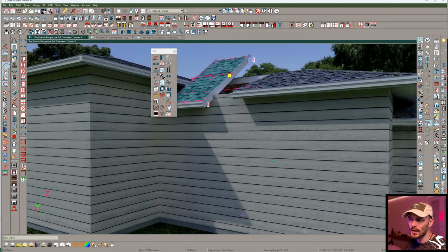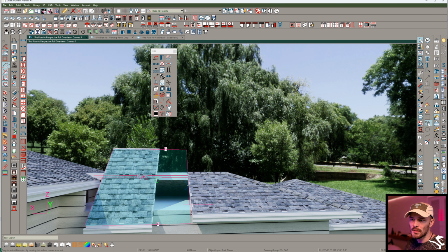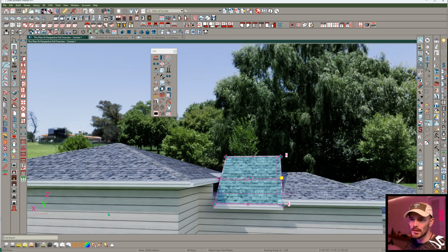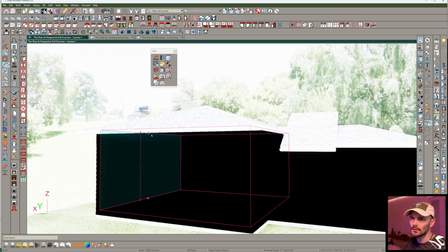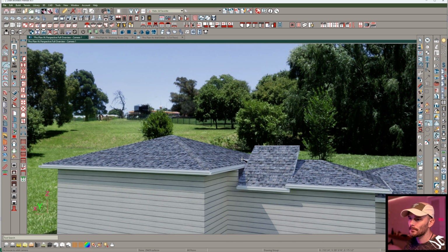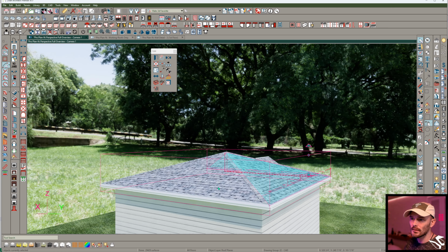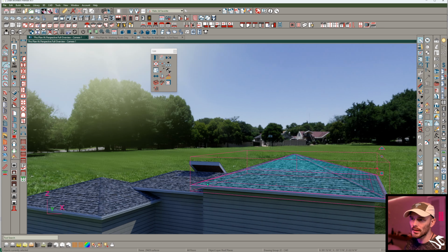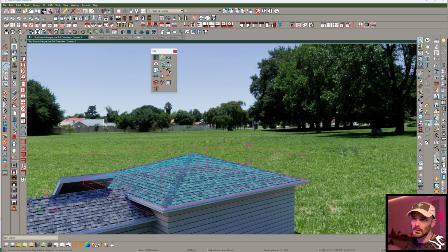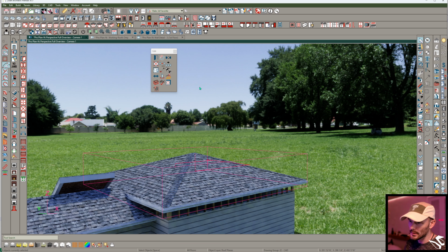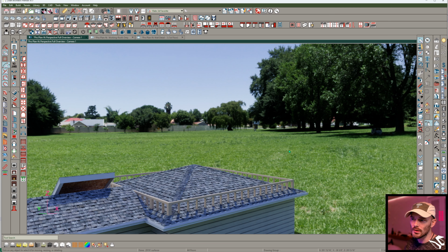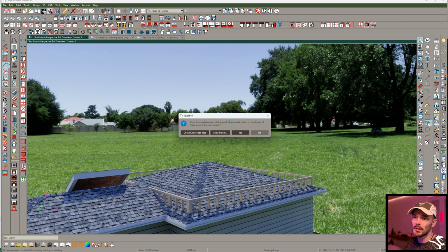There's two scenarios that happen. One scenario might be, and actually, I'm going to take this whole upper section here and I'm going to lower it. I think 2 feet to get it to line up with the section next to it. Okay. Now that I lowered that, this actually created just a huge heel height on all these roof planes for this upper roof. So I'm going to take all these roofs, use transform replicate, and I'm going to move it down 24 inches. It's going to change its relationship. What I want, and let's just rebuild all framing, that's fine.